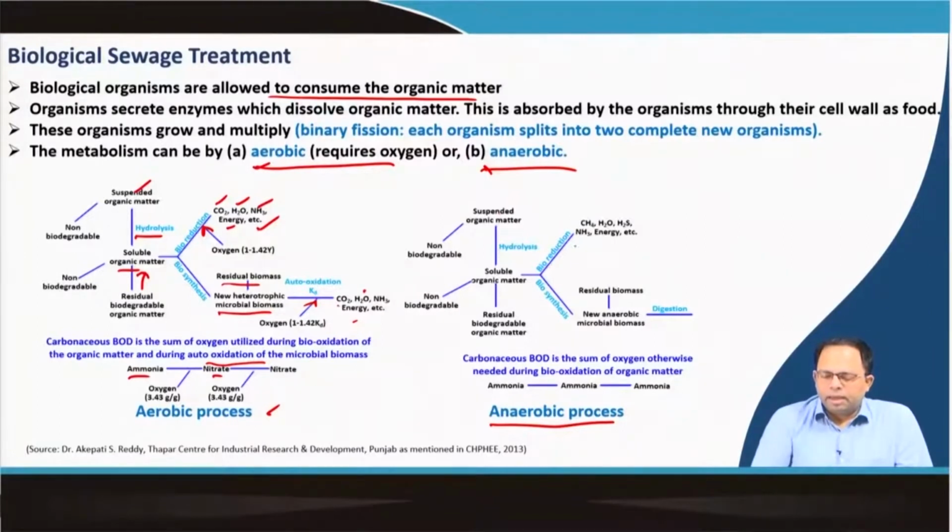The reaction that happens leads to formation of methane, H2O, H2S, NH3, and energy. So, instead of CO2 we are getting CH4, which is methane, and also we are producing H2S gas. So, if anaerobic conditions persist in a particular area, that means there is no oxygen, the decomposition is happening via the anaerobic process, then it leads to some bad odor, which is primarily because of this H2S gas, and it also releases CH4 or methane.